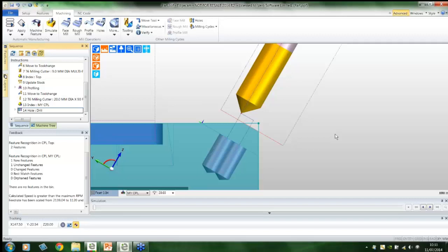But what I also see is that the drill cycle's lifted up, and that's made it clear for me. So otherwise, if I didn't have that enhancement, I'd now be chasing my tail, having to find the 20 or 30 drilling cycles that might potentially be there, and begin to change them. So this new enhancement is extremely important in 2014 R2.